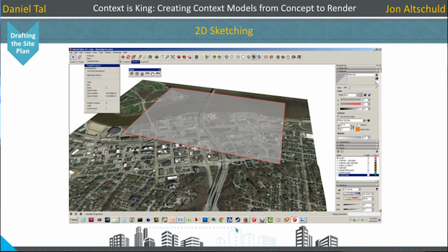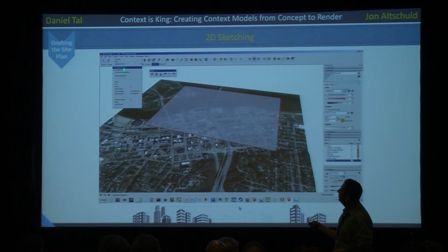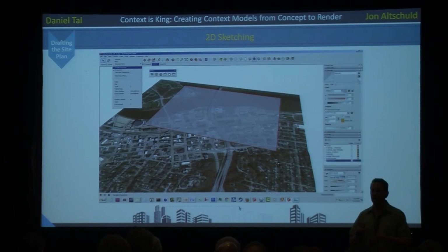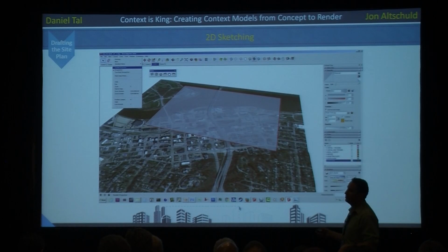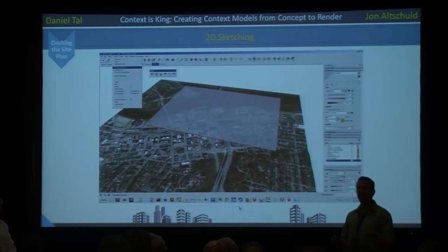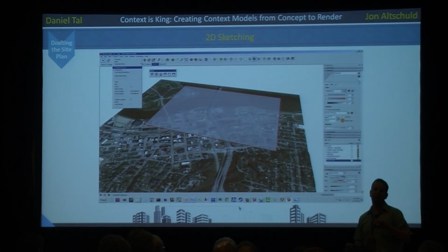So drafting plate, layer organization, and then we turn SketchUp into a plan view. So you go under camera, you make it parallel projection, and set the style view over here to top down. So we're in a true plan view. We create a scene for it, so just in case we accidentally rotate, we can go right back to that scene and tilt it right back. One of the interesting things, Concept Tools by Mike Brightman actually has a system built into it to automatically put you into a plan view system and also automate the creation of some of these scenes.